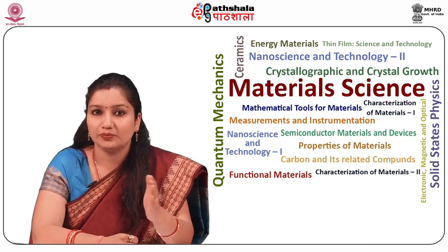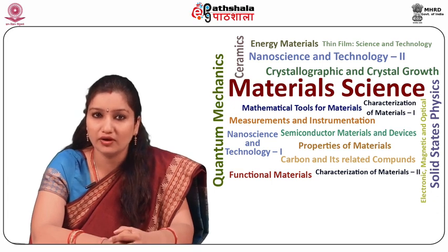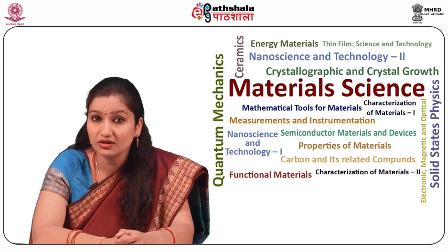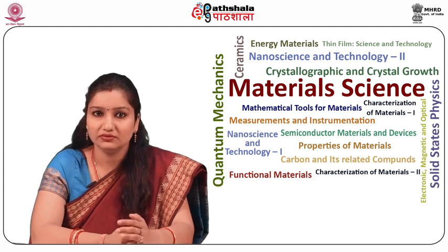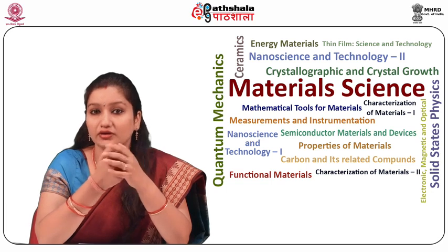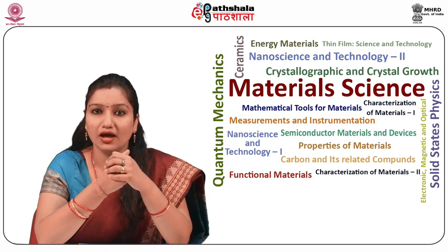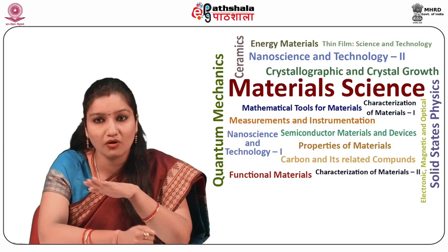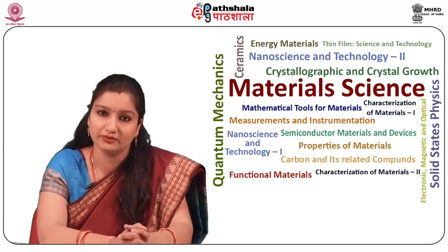Second point is the precise control of the surface finish by avoiding damage to the surface by rough machining, punching, stamping, shearing, etc. The third point is the control of corrosion and erosion or chemical attack in service, and to prevent surface decarburization during processing or heat treatment and the surface treatment of metal.